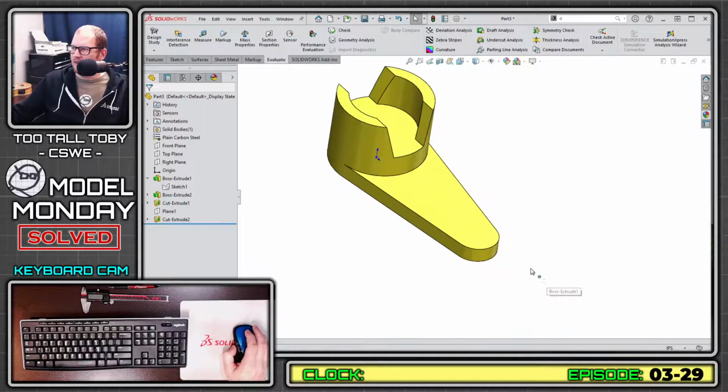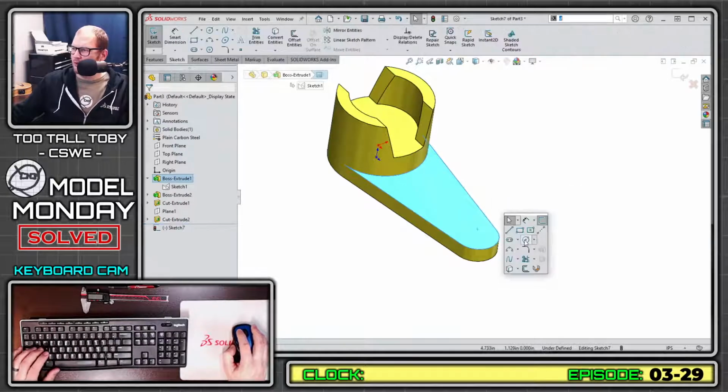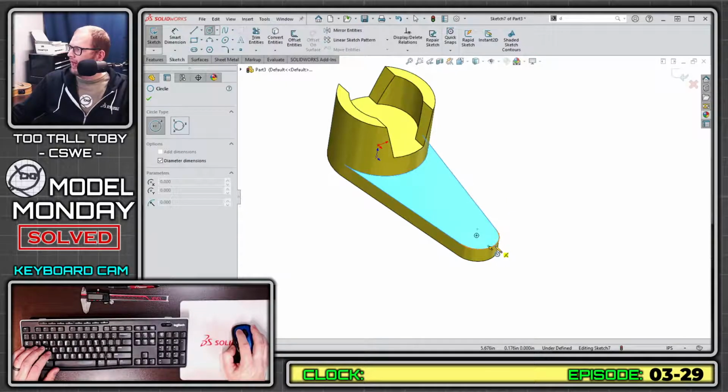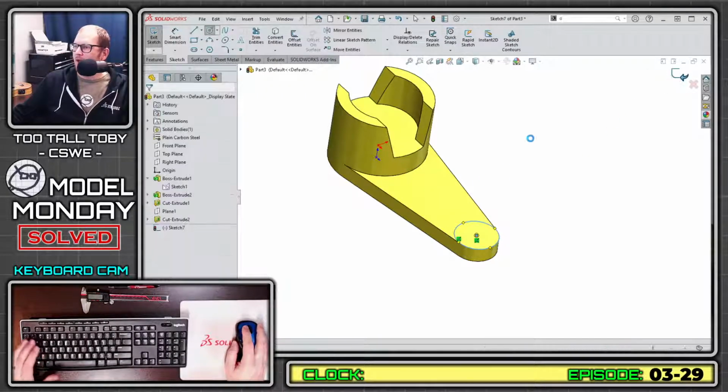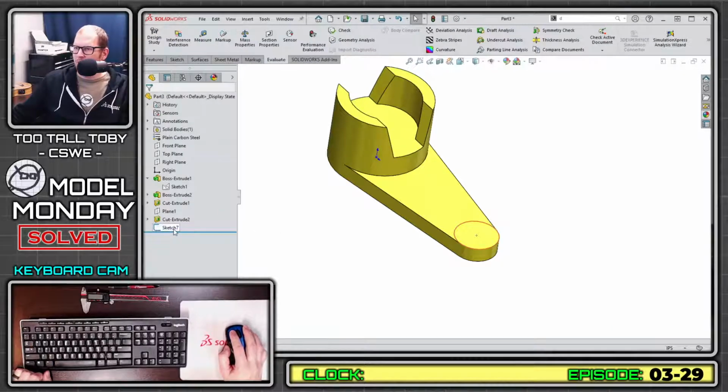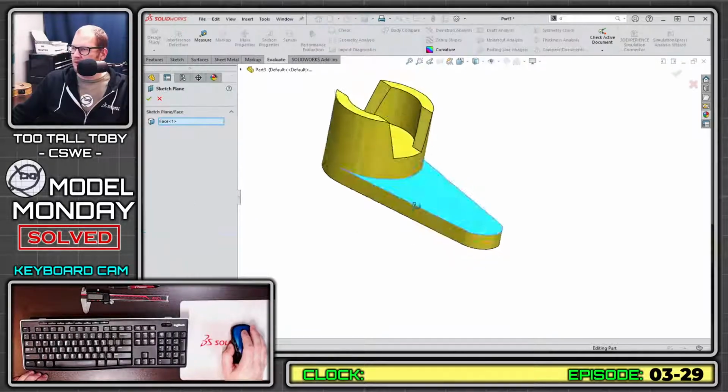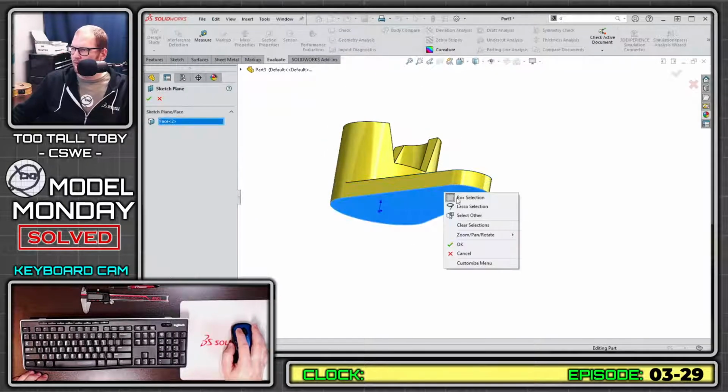Let's tackle this end down here now. Select face, begin a sketch, orient the view, S key. This one is, again, probably should have sketched it on the bottom surface. This one has a diameter of, it's a matching diameter. Sweet. Okay. Here what I could do is exit sketch, right mouse button on that sketch itself. And then when I right mouse button on that sketch itself, I can go in here to edit sketch plane and just push it down to this lower surface.